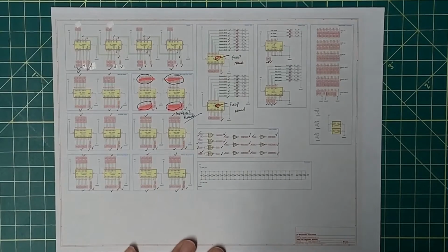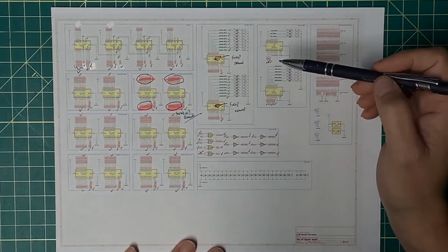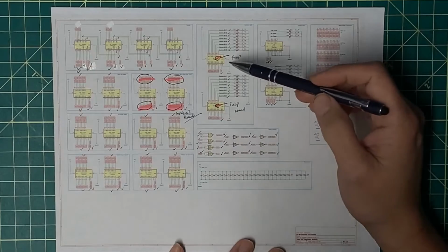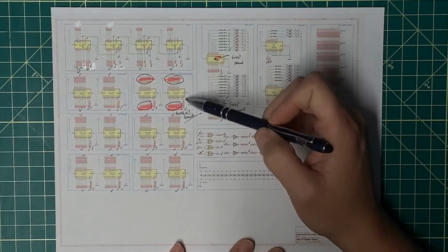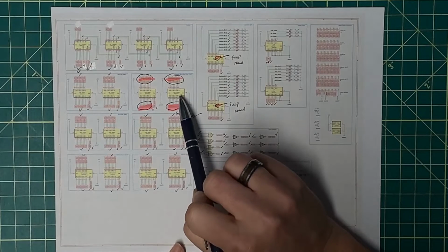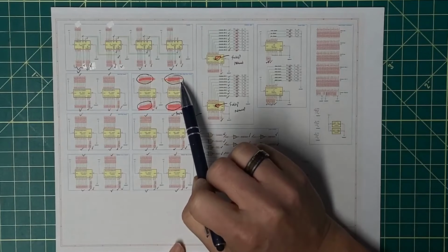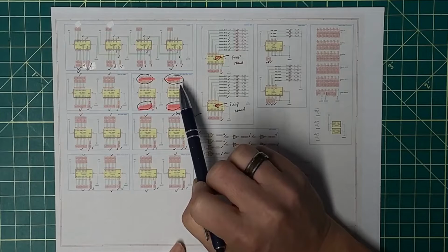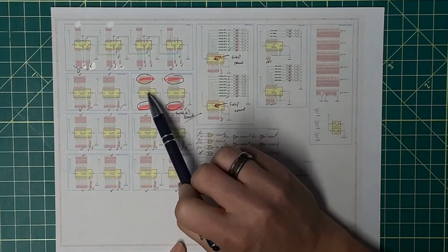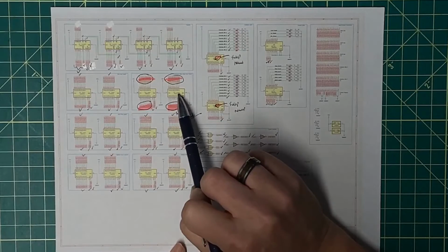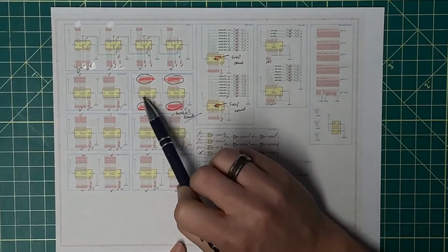Okay, and I really only found 2 problems here, and they are literally in naming. This will technically work, but I have the most significant bits that are going out onto the bus on the least significant side, so I want to take a moment and swap those, and it will require swapping the names of these as well.